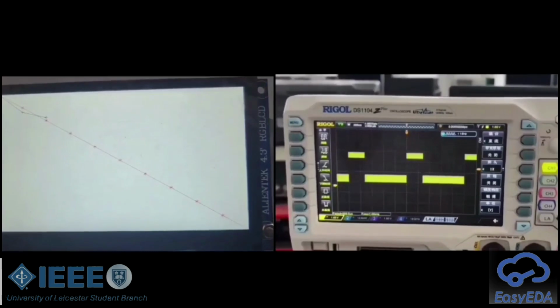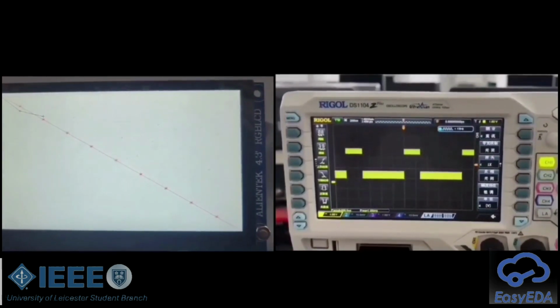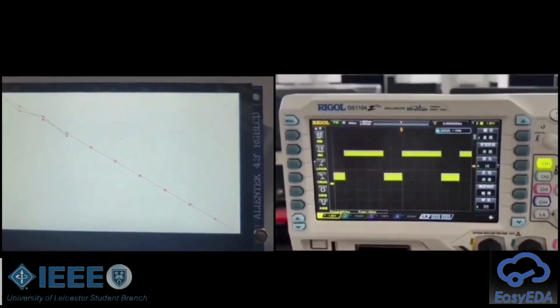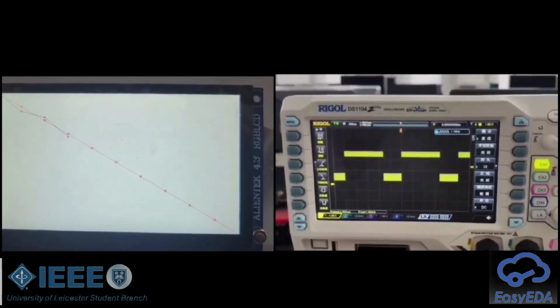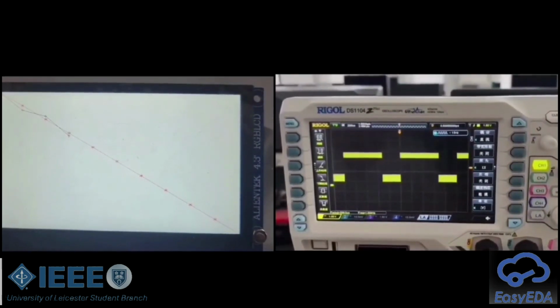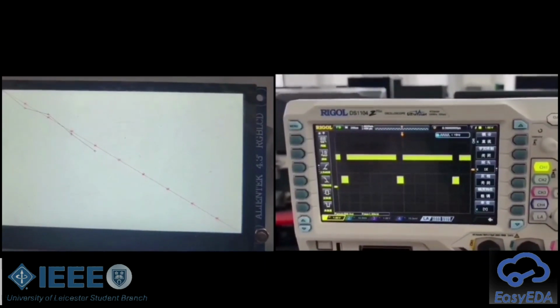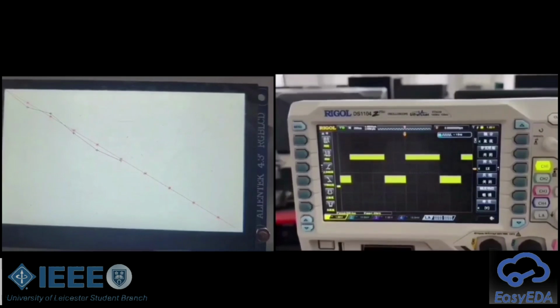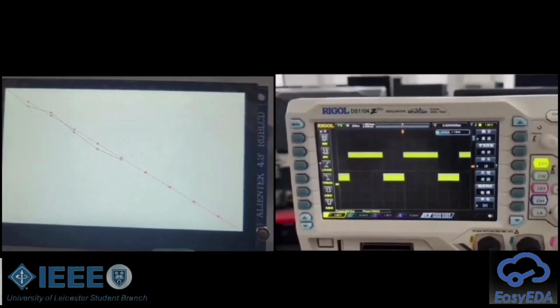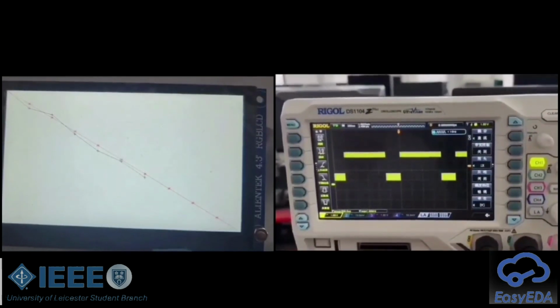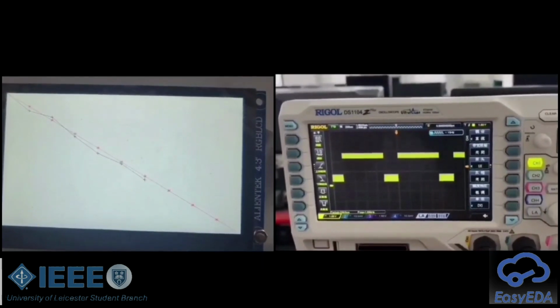After adjusting the slide resistor in the parallel step, the current increased, the power also increased, and the remaining power would be lower than the ideal remaining power. Therefore, during the next process, the duty cycle of the PWM will be reduced, as shown by the oscilloscope.